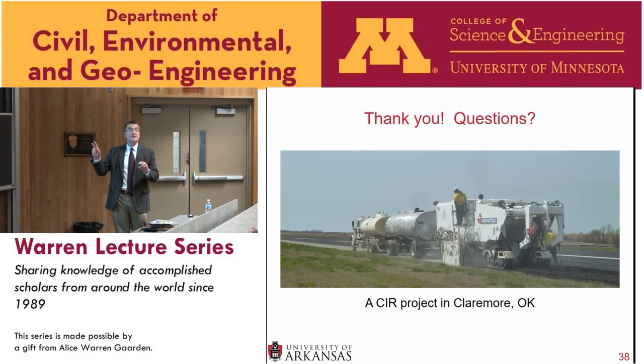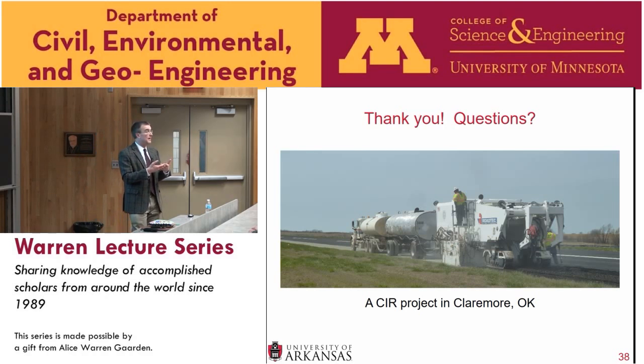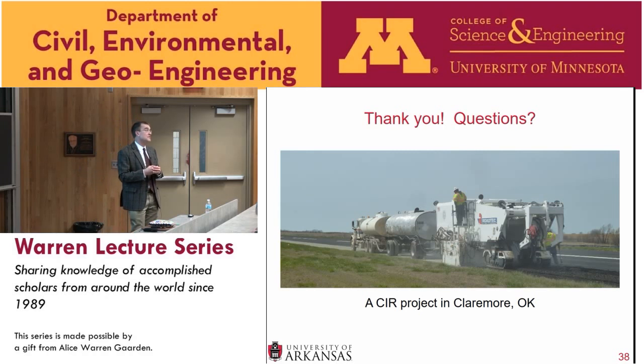So there's a couple things that are different from CIR. If you recall, CIR is 3 to 6 inches deep, so it's a little deeper. And with CIR, you're not activating that asphalt binder, because when you heat up asphalt binder, it becomes sticky again. It becomes cohesive again. So in HIR, when you heat it, you can add chemicals that can actually chemically change that asphalt binder, and that's very difficult to do if you don't heat the rock. So I would say that the 2 biggest things are you can't change the properties of the asphalt binder as well with CIR, but you can go deeper with CIR.